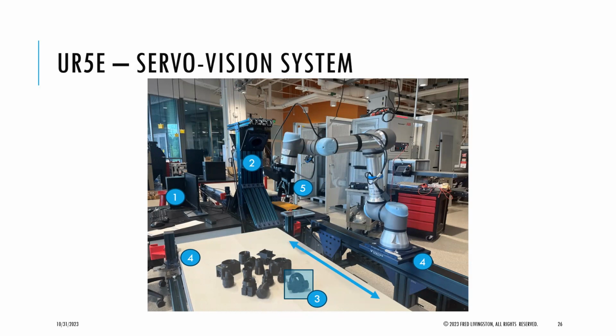This is my end effector. And we could connect these here. And there could be some tool there. And so that is my gripper, which I'm calling 5 here. And it has a camera attached to the robot, and it's really pointed in this direction. This is some kind of offset here, and it could be a rotation too. Let's say this is my z-axis now, and I detected the object. It's probably at the same height. I'm going to call this object 8 here.